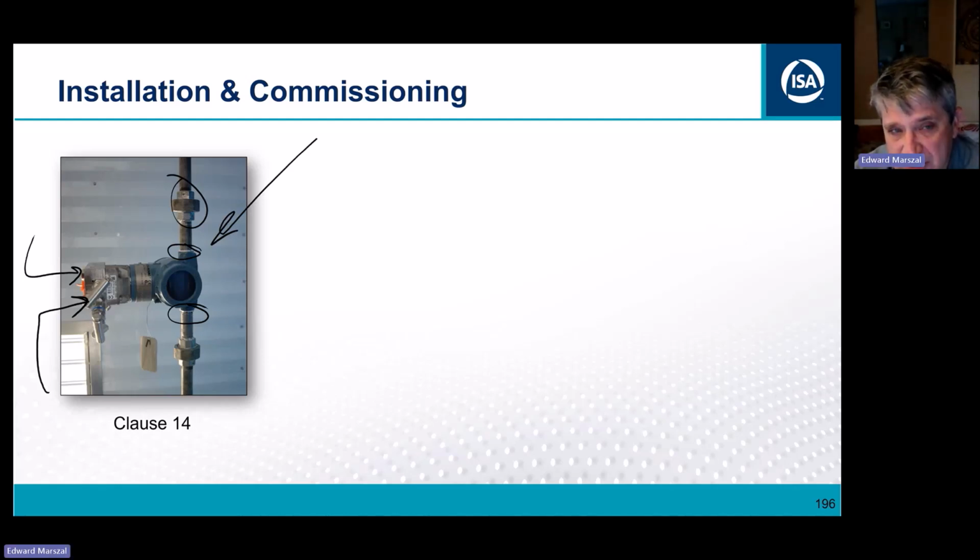As a matter of fact, I'm going to show you through the rest of this webinar that trying to include the frequency or probability of human error in our SIL verification calculations not only is not going to be helpful, it's actually going to get us to do the wrong thing. It's going to trick us into making a bad situation even worse.